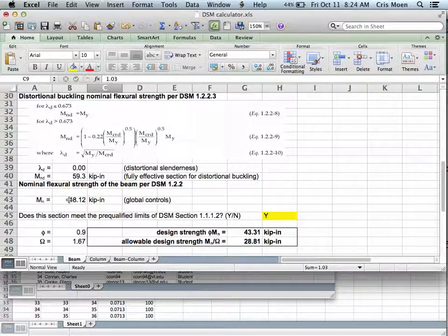Any other questions? Would you handle a pre-fastened panel in the same fashion? You would, except the translational spring would be just a pin. It would be infinity. You put in a really high stiffness, or you could put in a pin in CFSM. The rotational spring still has a certain value that we have equations for, based on the thickness of the panel and the shape of the panel.